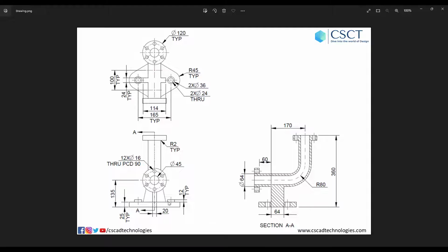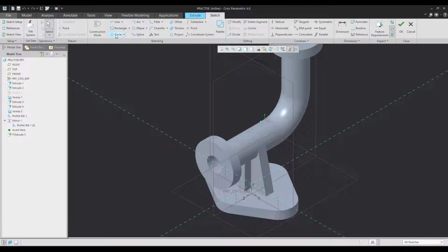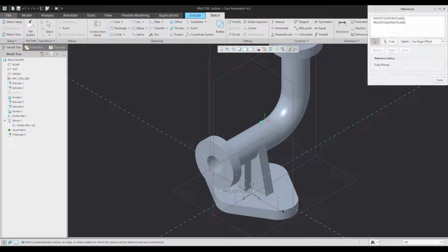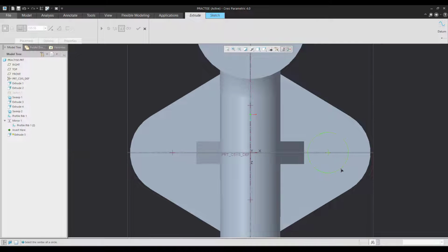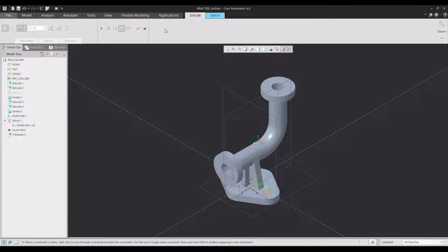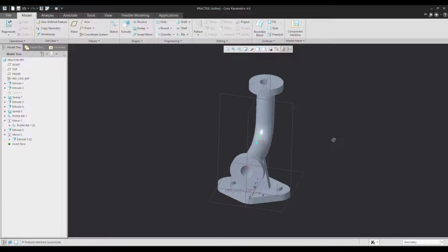There are also a few welded parts which are of 36 dia. So let's try to do that as well on this face with this as my reference. Take the sketch view and then start making your 36. This is actually added up to 12 mm. The same thing can be mirrored onto the other side as well, and this is your mirror.